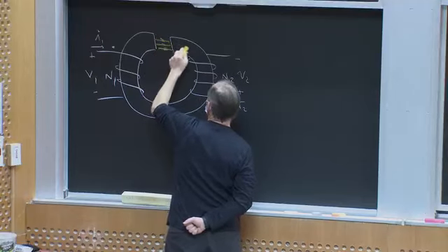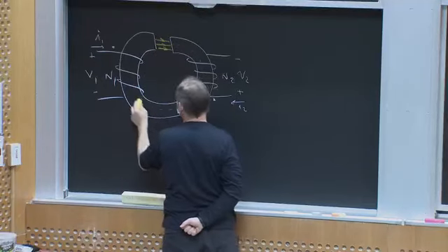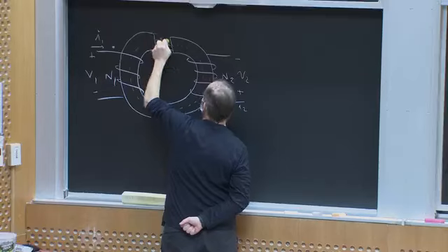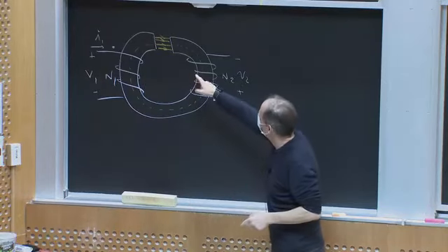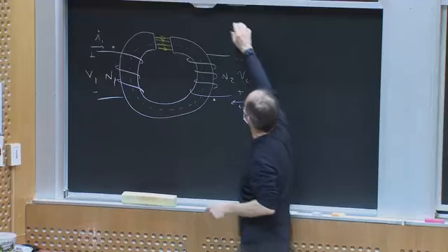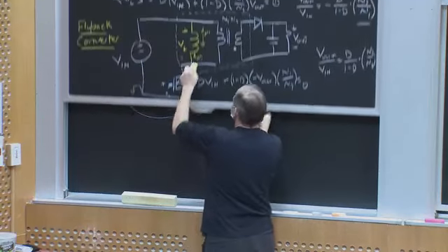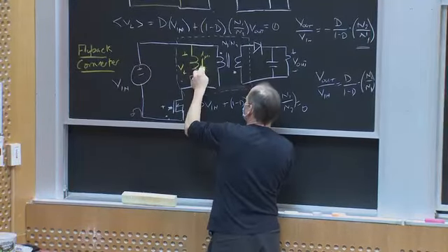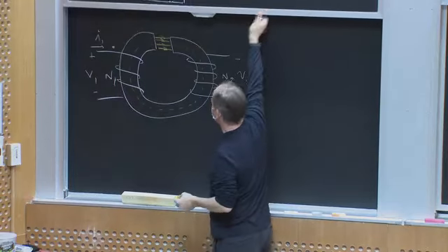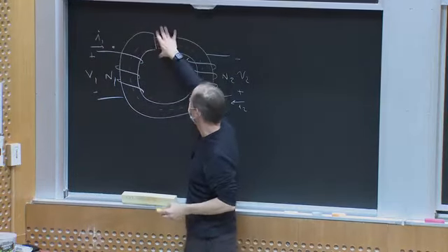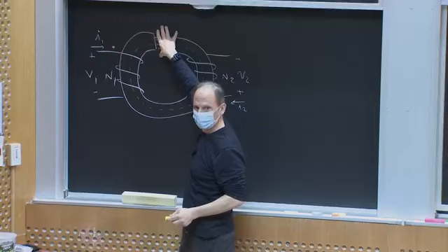So maybe there's a tiny bit in the core, if this is H that I'm drawing, but most of my energy is stored here, okay? How is that reflected in this circuit diagram? It's reflected in the magnetizing current, right? 1/2 L mu1 I mu1 squared reflects the energy stored in the core and in this gap. Okay, mostly in the gap. Make sense to everybody?